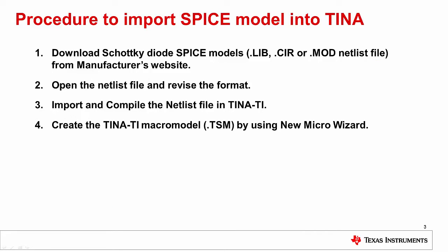There are 4 main steps for importing a SPICE model into Tina TI. First, download a Schottky diode SPICE model from the manufacturer's website. Second, open the netlist file and revise the format. Next, import and compile the netlist file in Tina TI. And lastly, create the Tina TI macro model by using the new Macro Wizard. We will cover these steps in detail.